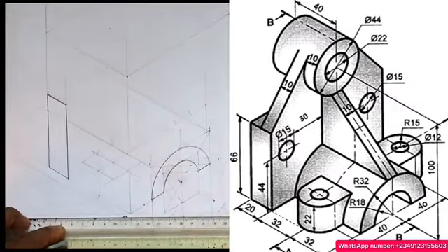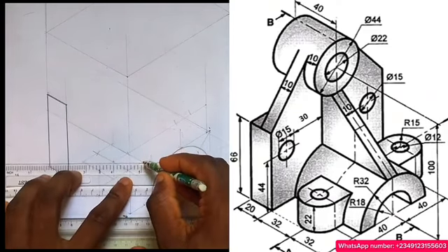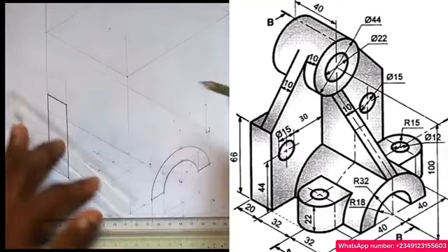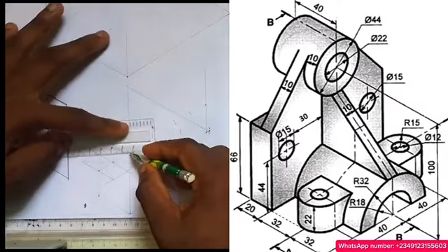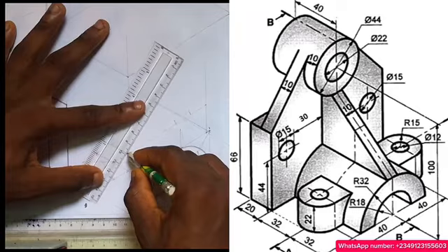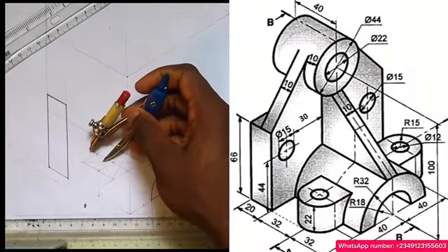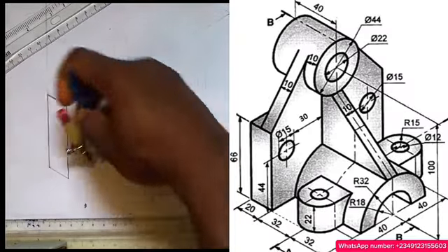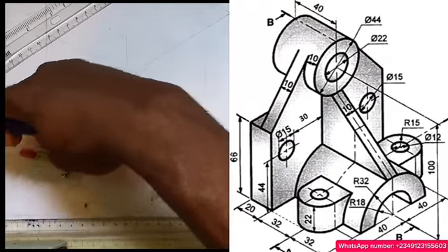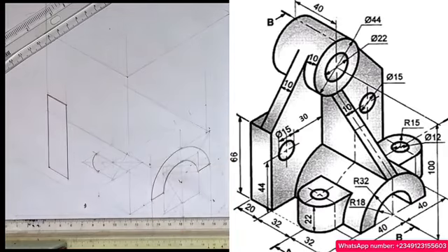My task now is to also draw the longest diagonal, so here to here. Then I'll use my ordinate method. Connect here to this point, right? And I will connect here to this point this way. So I'll create the first curve there, right? Come to this point here. I'll connect this to this curve, this to this, right? So this way, I have this.